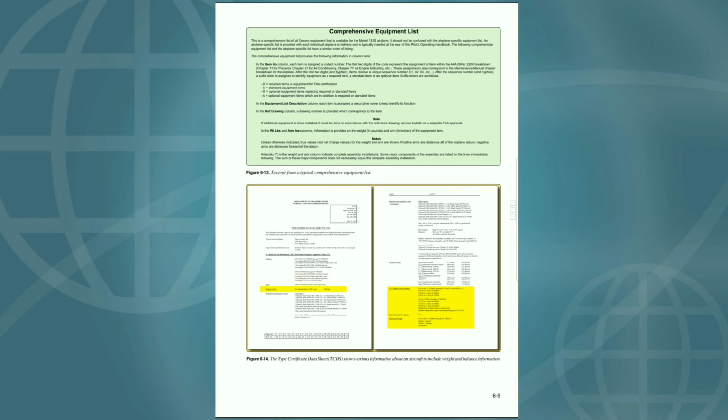Fuel: 100/130 minimum grade aviation gasoline. Engine limits for all operations: 2,700 RPM, 200 HP. Propeller and propeller limits, left engine: 1 Hartzell hub model HCC2YK-2E, blade model C7666A-0; 1 Hartzell hub model HCC2YK-2EU, blade model C7666A-0; 1 Hartzell hub model HCC2YK-2EF, blade model FC7666A-0; 1 Hartzell hub model HCC2YK-2EFU, blade model FC7666A-0.